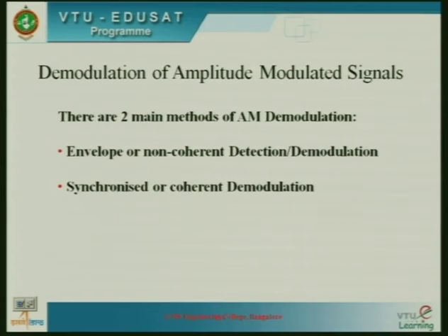As we were discussing, there are two kinds of demodulation techniques: envelope detection and synchronous detection. In envelope detection, there are two different techniques to be understood. One is based upon the diode envelope detection logic. The second one is based upon the square law model. In both the models, the signal that is coming from the channel is directly fed into a demodulator. The diode and the corresponding resistors and capacitors are able to extract the message.